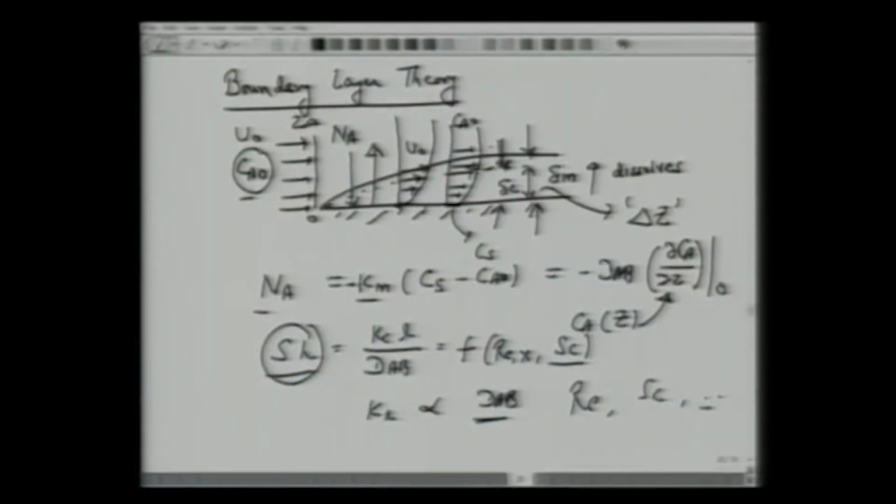whether it's a flow in a packed bed, or mass transfer over a flat plate, or you have the interface of gas and liquid, you're supposed to go through the table of Perry's handbook and get the correct correlations, calculate Reynolds number, calculate Schmidt number, or any other restriction which is given, to ensure that you are using the correct expressions for Sherwood number to calculate these mass transfer coefficients. All right. So this is the end of your introduction to diffusion and mass transfer.